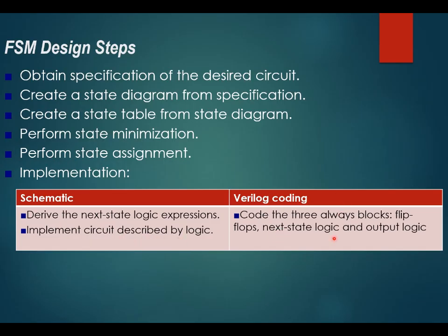If you use Verilog coding, then you don't need Karnaugh maps. You just code it based on one of the simple methodologies where you code 3 always blocks. The first always block represents the flip-flops or state registers. The second always block implements the next state logic, and the last always block implements the output logic.